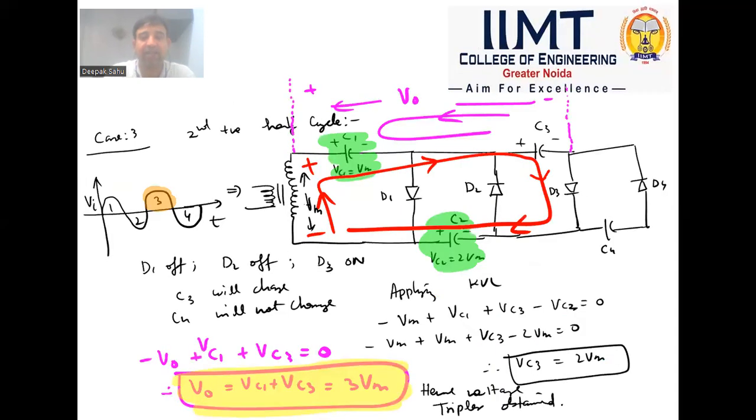So now moving on to the next half cycle, keep paying attention to the input. Now the first time period has passed and 2 capacitors C1 and C2 have been charged till now, which are shaded in the green section. Now the next cycle begins with area 3 shown here, which is our second positive half cycle. So the polarity gets reverted again. Now this plus cannot forward bias D1 since the capacitor's negative plate is directly connected to it. So in spite of the plus here, diode D1 does not get on. In the same way, capacitor C2's negative plate keeps its diode from getting on.